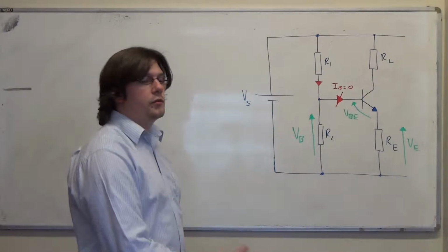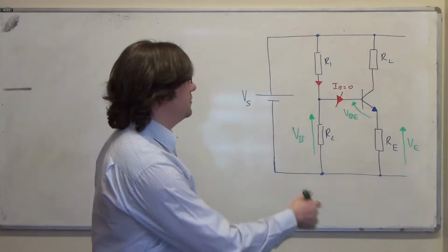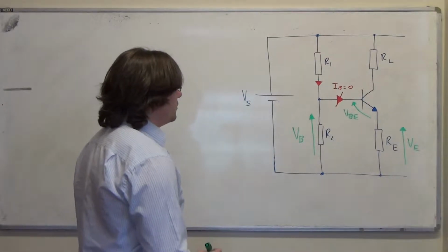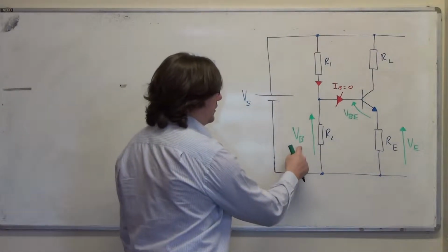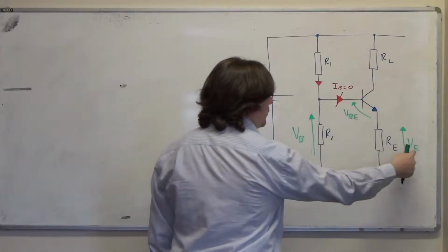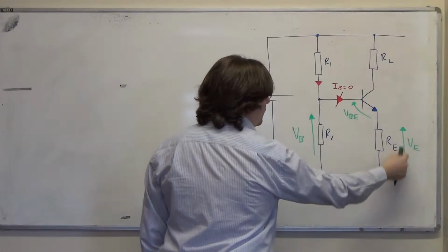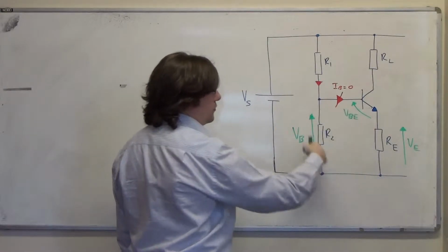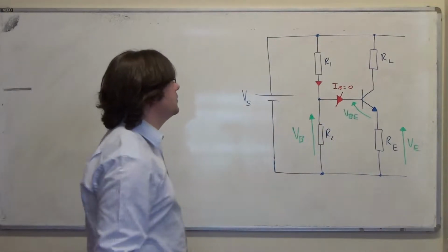And if it wasn't, I probably wouldn't have called it the emitter resistor, because it's nice and self-consistent. So that's one loop, because we know that VB has to add up to VBE plus VE, because that voltage and that voltage is the same as across there, so we've got a loop of voltages and they all have to add up to nothing.